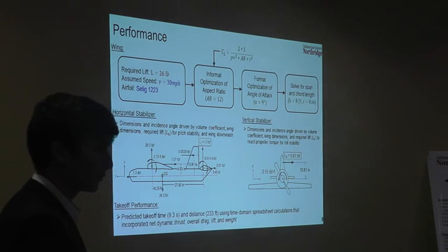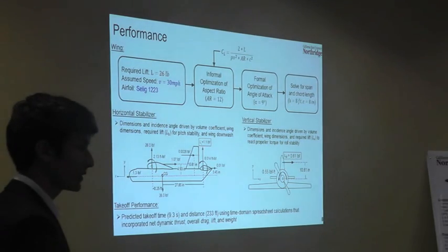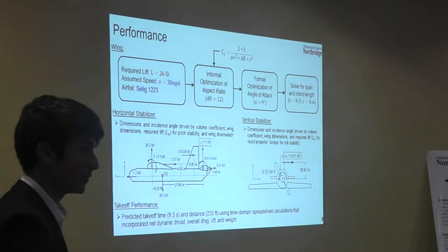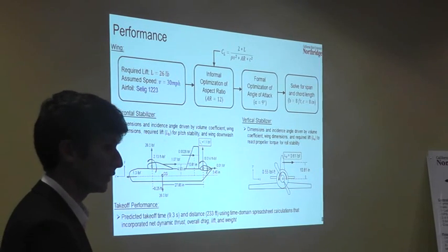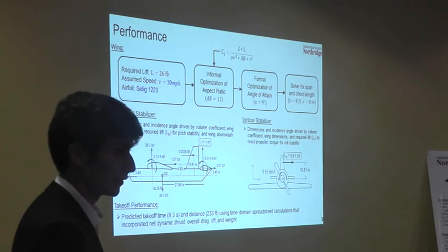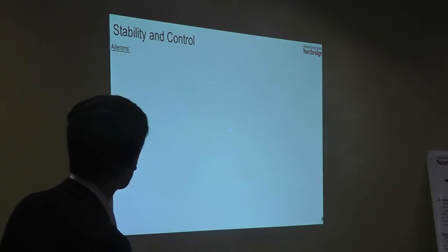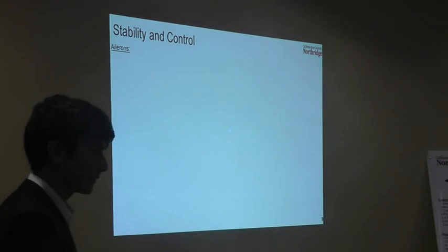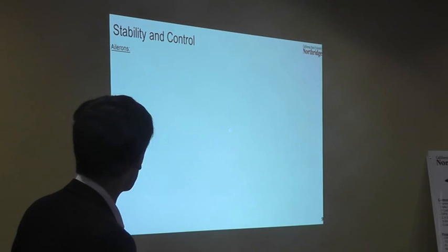To summarize the takeoff performance, the takeoff time is about 9 seconds in about 230 feet, and we did this using a spreadsheet calculation that incorporated all four major force inputs on the aircraft. The stability and control of the aircraft is governed by the roll, pitch, and yaw.